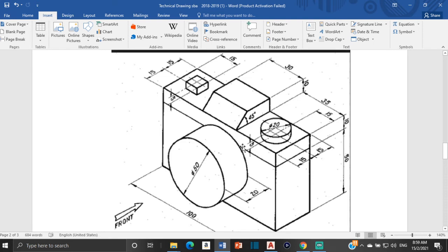Now, when I did the isometric projection for this, I had to draw this line at 60 degrees. Why did I have to draw that line at 60 degrees? The reason was because, as you know, in isometric, lines are drawn at a 30-degree angle. So for this angle right here, this line would be at 30 degrees, and then the next line here is at 90 degrees.